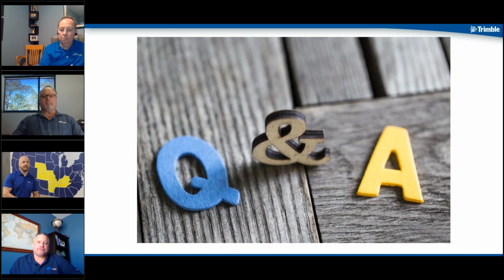Very good. And I would add to that, Sean reminded me of a point. I was on a job where somebody put those on an adjacent parking garage, and they put it in the middle of the spandrel panel. Depending on the time of day or what size the vehicle was that drove by, that spandrel is going to change. So keep that in mind too. I'll just throw out my advice: with parking garages, unless you're putting it right in a corner or right on a column, that's a bad location to put those targets. So just be smart about where you're putting those. If you can, put it on an inside or outside corner, or right where a column is, that's one of the best places to put those.